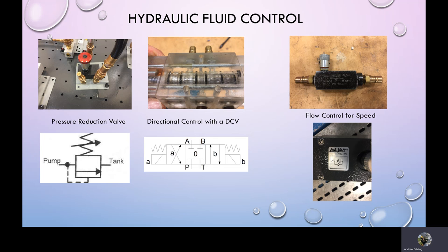However, the system air in the plant is at 100 psi, or approximately 10 bar. And at the point of utilization, I might only be using 3 bar in the machine that I'm using. So I can dial that pressure down. Basically, in a centralized loop, I would have the pressure on my pneumatic system cranked above the largest or the highest pressure required in the system, and I would dial down all of the other drops for individual machines from that high pressure feed.